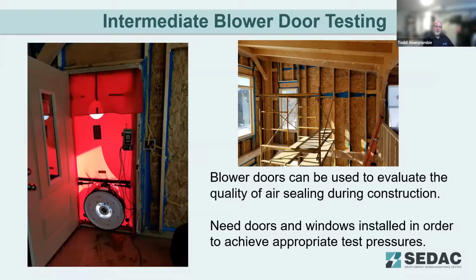And then here's something I call intermediate blower door testing. If you're in a situation where you need to get a blower door test, it doesn't have to be done after drywall. Generally speaking, that's usually when we do it because that's the final of the job. But I've had some clients building some new homes. In this case, this was one of them you see in the picture, where we came in and did the blower door test before any insulation was installed. And in this case, they had a SIP ceiling, so we didn't even have to put drywall on the ceiling.